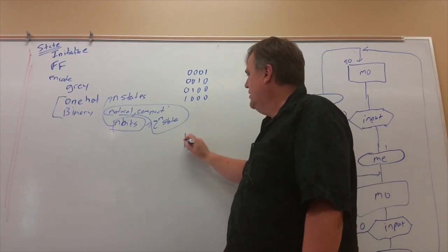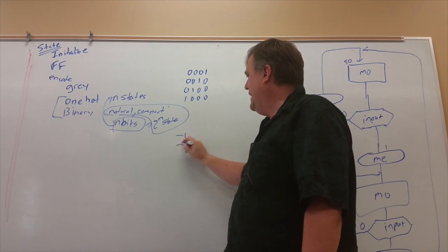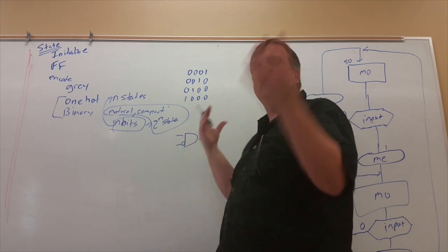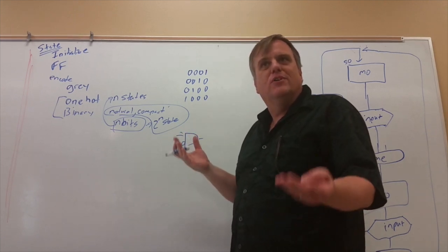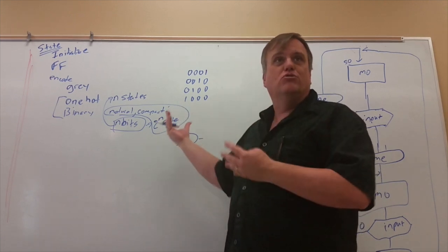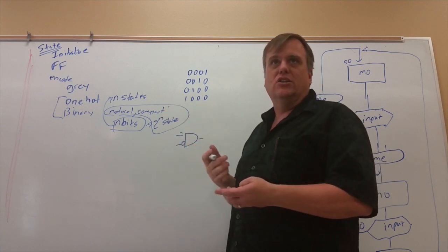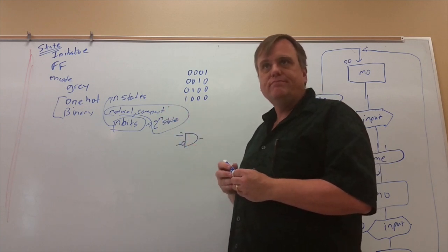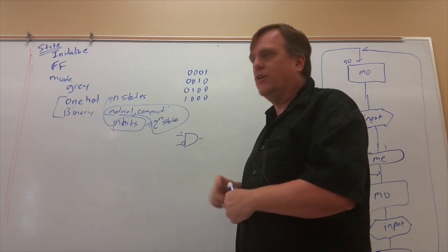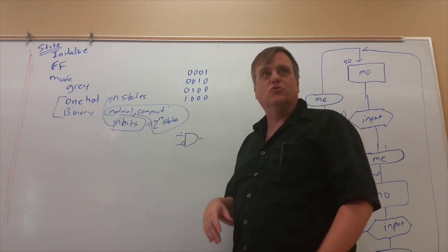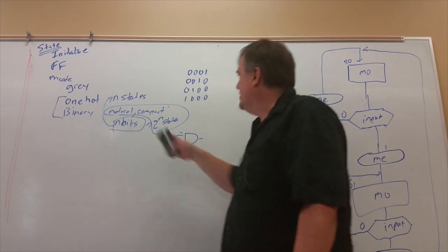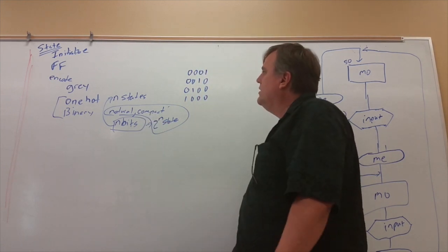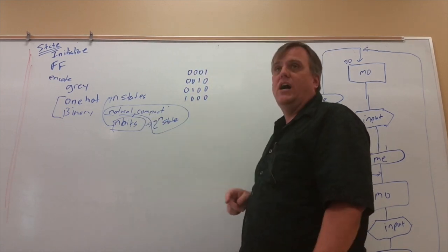State 2 is just going to be that. There's your decoder. Right, looks for a 1 and a 0. But as it grows, that gate is going to get uglier and uglier. Right? And fan in will start affecting you, and you'll have to go to multiple stages, which increases your latency. So this gets slow. All right. So this is the idea with one hot.